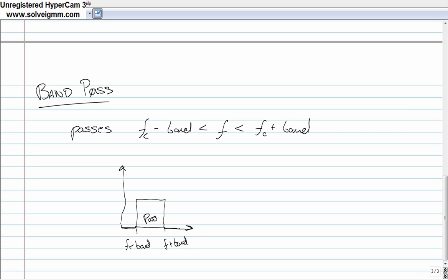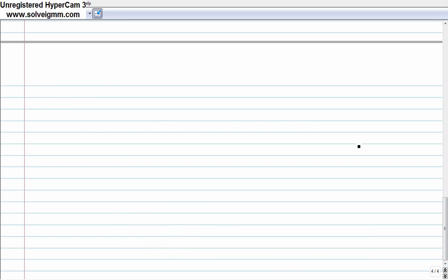Okay, from here on out, it's going to get very mathy, and this could be quite a long video, so I'm just warning you now, this is going to get a little head-hurty. So let's talk about low pass first. It looks something like this. It's got a resistor, and then it's got a capacitor attached to it. Here's the input, here's where the output is, here's C, and here's R. In this case, order matters. Note that the resistor is first, then the capacitor.